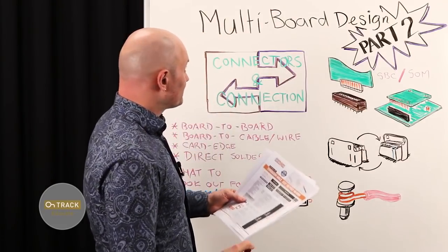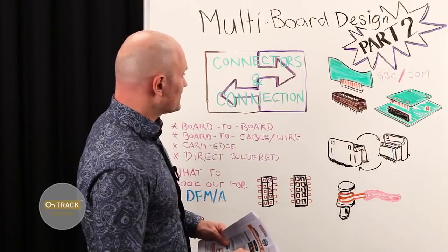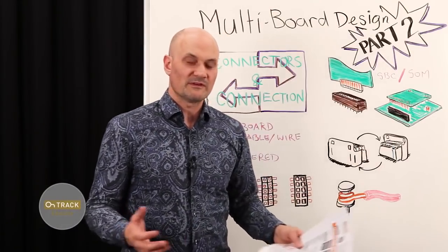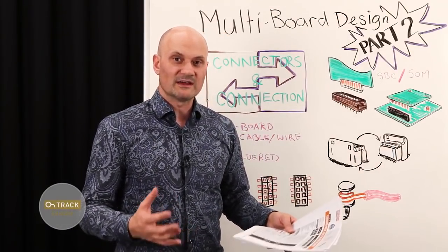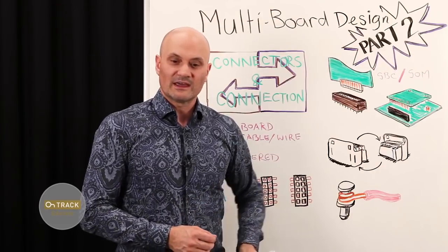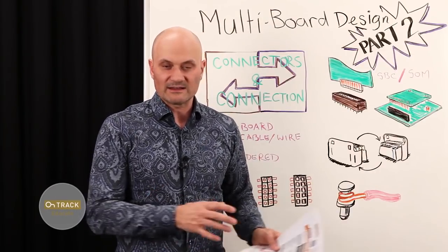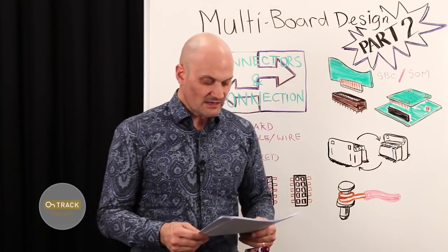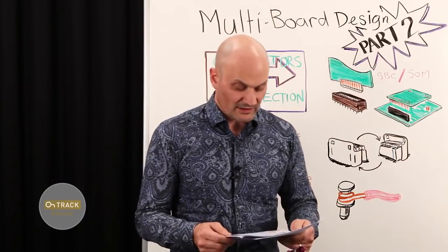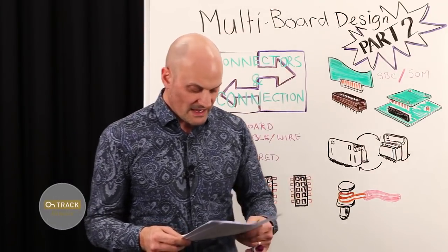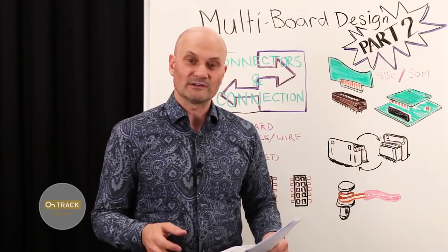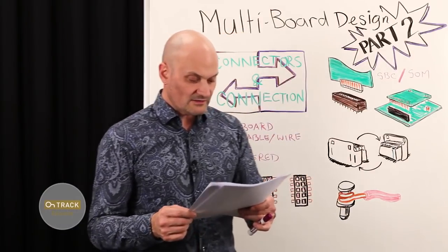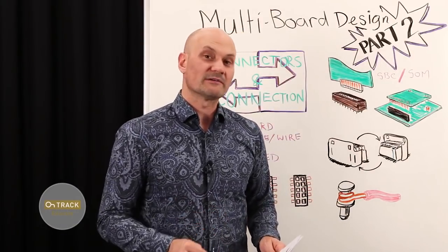Next, let's talk about duty cycle, because the other thing with multi-board systems is one reason to do a multi-board system is to fit the whole thing into a smaller enclosure to get more electronics into the right shape. And if that's the case, where you're just connecting everything together and then shipping it off and it never opens again or is touched, then you don't need a very high duty cycle. So you want to look at the manufacturer's recommended duty cycle limits for the connector. Now, usually there's a pretty broad margin on these, but it's about what they agree to be held accountable to.